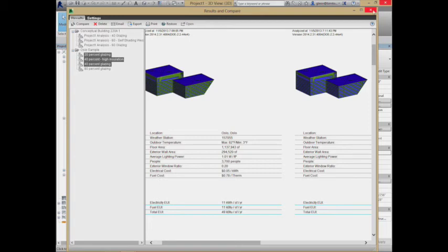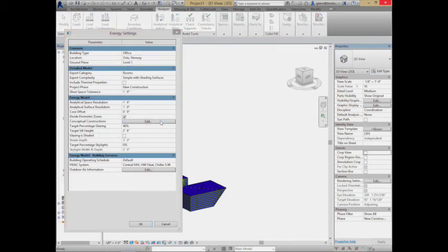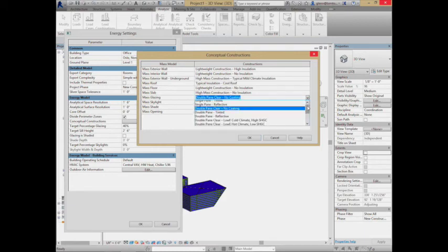So if I wanted to try changing something about the window efficiency, I could go look at those conceptual assumptions. And as opposed to just the standard windows, where's the glazing? There it is, double pane windows. I can say, what would happen if they were triple pane windows, or had some low E, low solar heat gain coefficient for a cold climate.